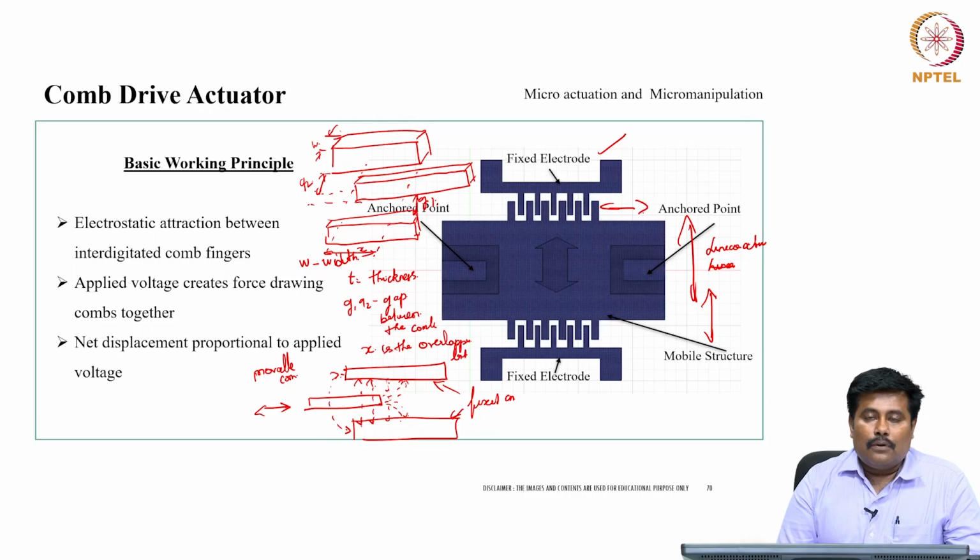Voltage controlled comb drive actuators are quite attractive in micro positioning because the lateral electrostatic force is independent of the position, contrary to parallel plates.